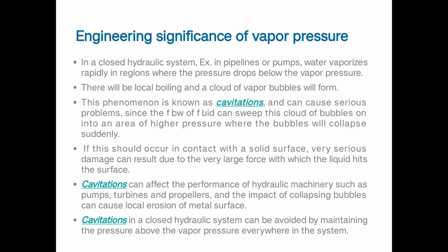So this will not allow the proper performance of the pump, which means the pumping speed and the other mechanical energy to be maintained by the pump will not be maintained. We call such a phenomenon cavitation. Got it? Cavitation.